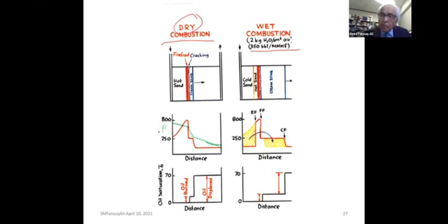Now imagine that we are injecting some water. What happens now is that the water will pick up the heat from the hot sand, and it will create a steam zone further out here. So we are still leaving some hot sand. We are not completely cooling it down. Now the second diagram shows you the pressure. The pressure is very high here, then it goes down.